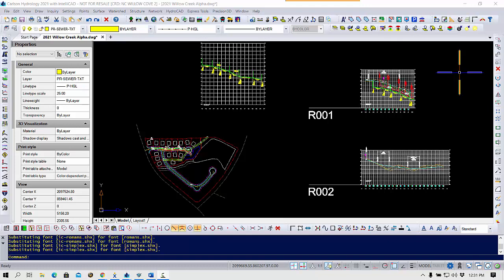The Rational Rainfall Library uses IDF curves to provide average rainfall intensity data for particular storm events. With a known rainfall duration and frequency, an intensity is calculated via the IDF curve and applied to the rational method to obtain the peak flow for designing the sewer network. This data can be downloaded directly from the NOAA National Weather Service website.